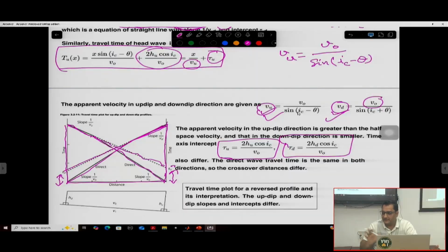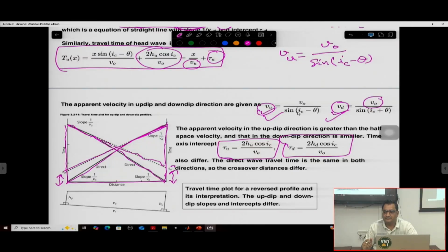When we do our survey, we have a number of geophones placed along the line. Okay, so on all the geophones we are recording our energy. So X is basically varying. When you want to cover a larger line, you can move in the roll along mode and keep on doing your survey, keep on shooting, and thereafter you collect the data. Okay, any other question?